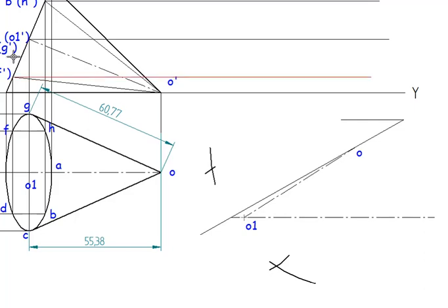Now similarly I am going to take the distance from O1 to H, which is 18.94. I'll draw an arc with the center point from here, 18.94. I will cut an arc.